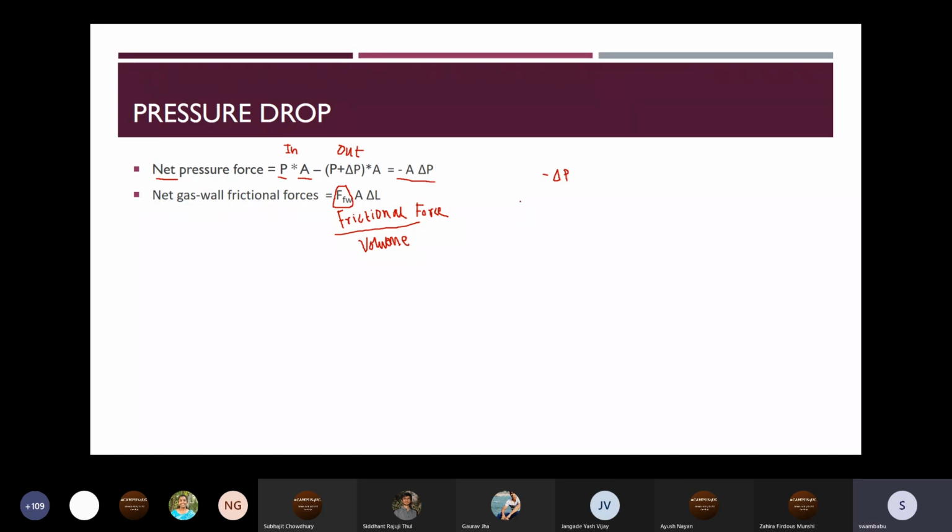Since this is pneumatic transport, we have particles and the fluid. This is usually multi-phase flow. Different flows are included together: one is solids, another is gas. We have two phases here, one is gas, another one is solid. Since multi-phase flow is very complicated and often very difficult to derive from the fundamental equations, whenever we have this difficulty in expressing from the fundamental definitions, we have the empirical correlations.